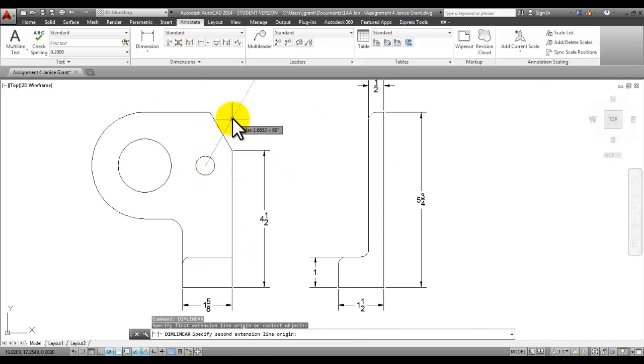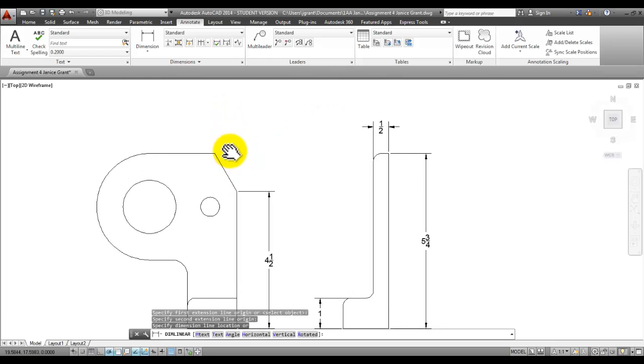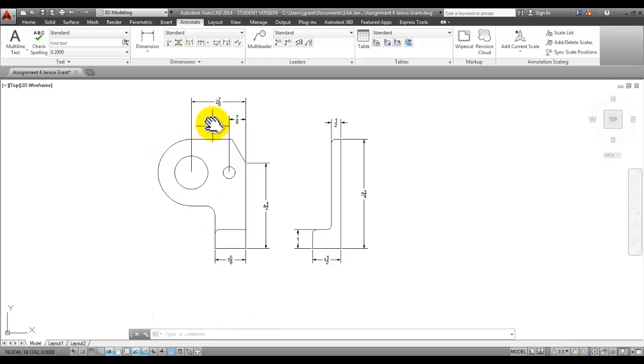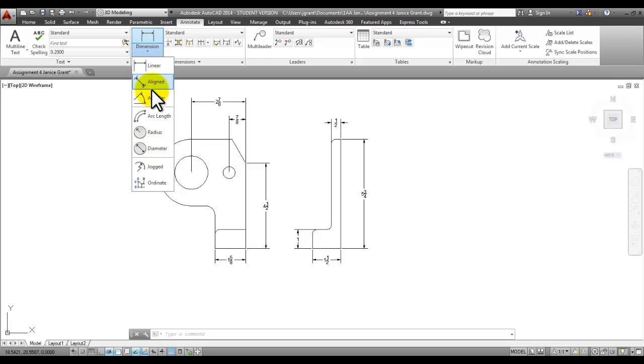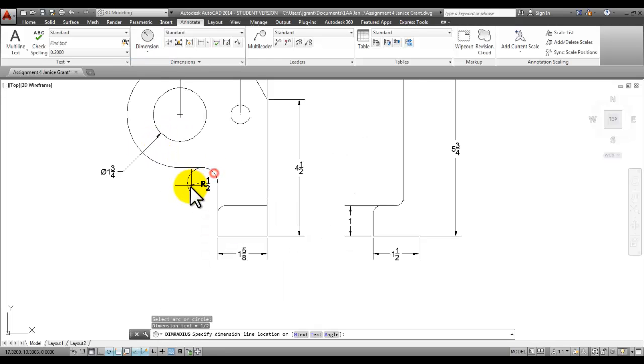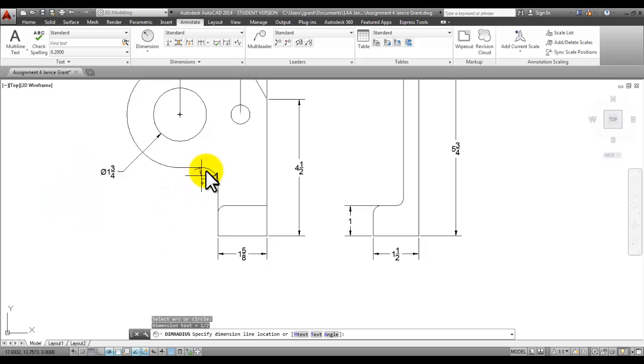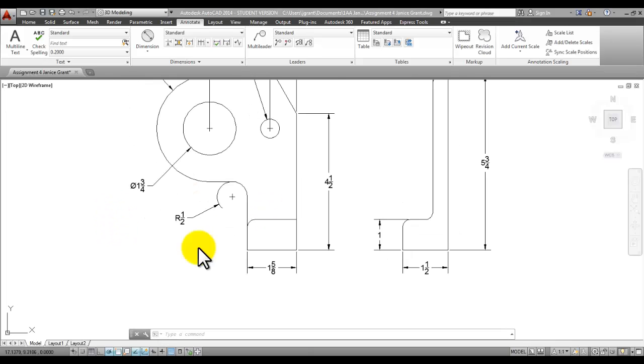And we have here a center of circle for these dimensions. And some people, for the radius dimension, will go to the dimension drop down and use here radius or diameter. You can even use it for this radius. Now, this is the part AutoCAD has set up for some reason. When you use this tool and you pull your mouse to the left, you've got this extra small line here. There are a couple of different ways you can fix it. So once you place this radius here using this drop down, you could fix it, or you can just use